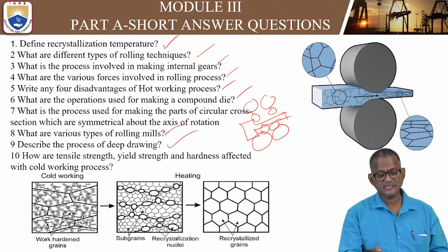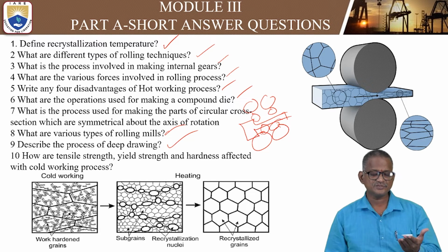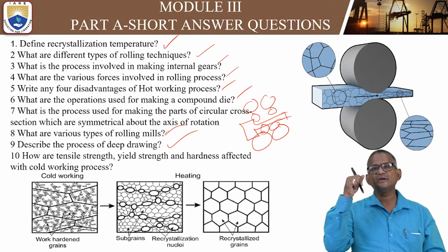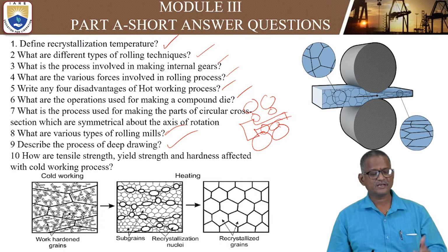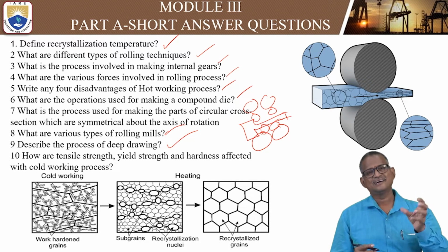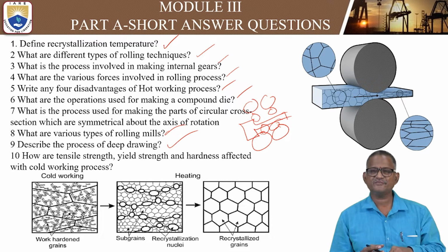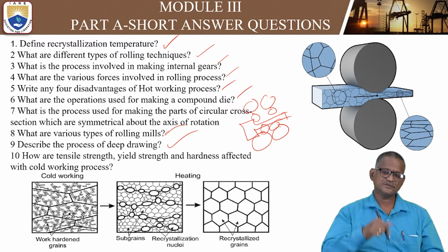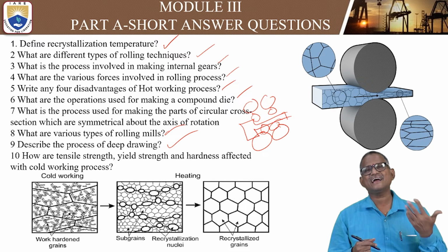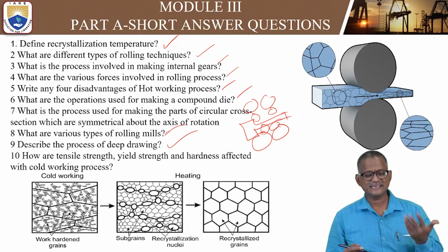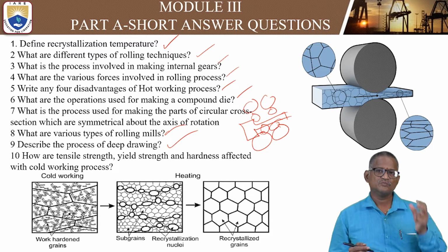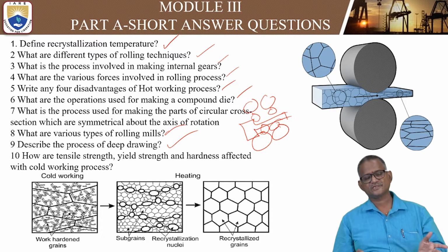Similarly, consider cold working. Cold working needs more pressure because there is no heating, so the structures and grains cannot be modified. You can apply pressure only. Due to more pressure applied, work hardening and strain hardening will occur. Sometimes more pressure leads to breakage also.